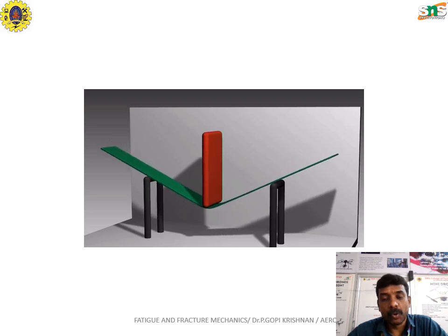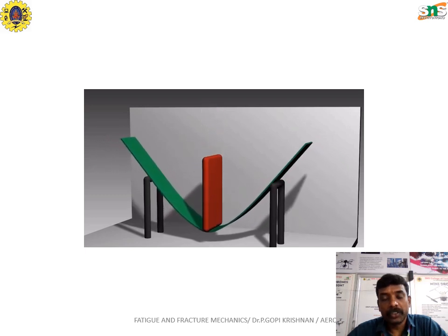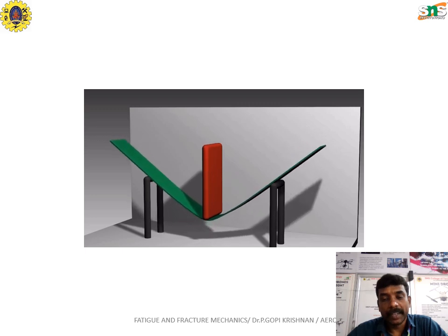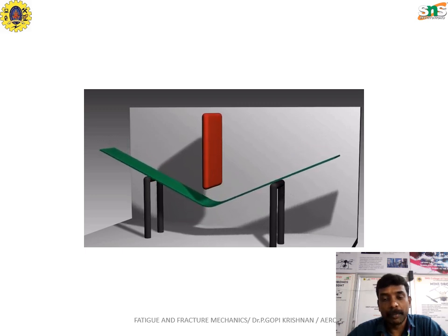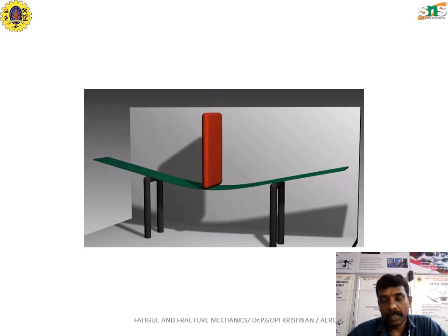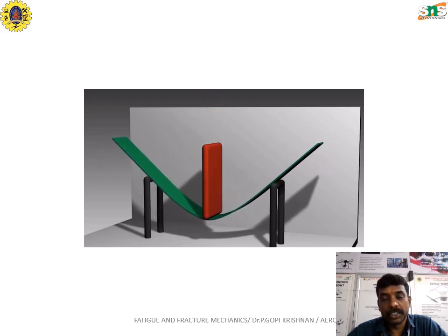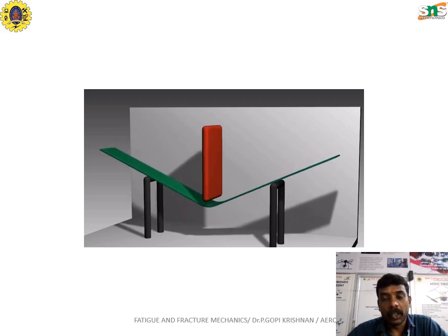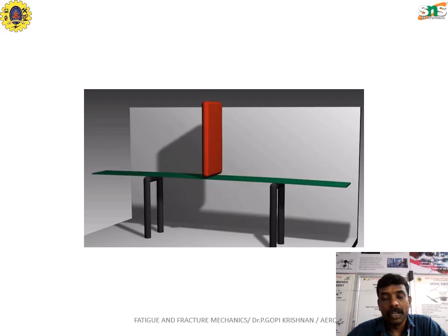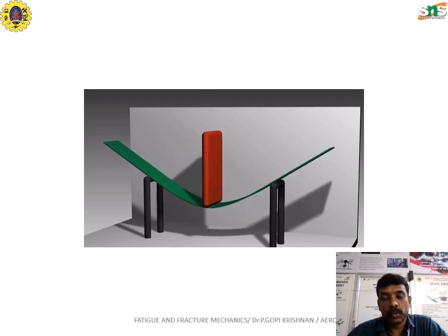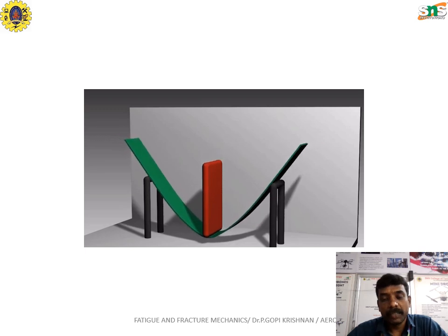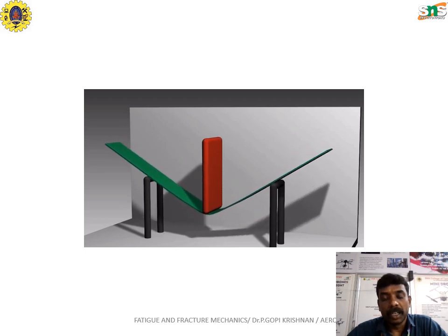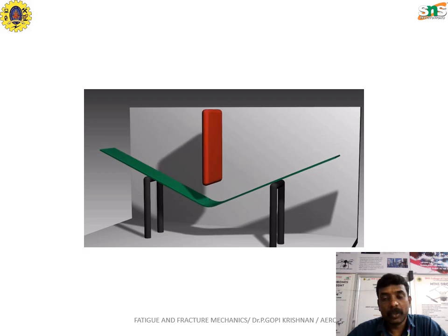In the picture given, if the same kind of force is applied over the sheet metal, in the top surface the force acting over the system can be called the compressive force, whereas the opposite side, that is the bottom side of the sheet metal, experiences some kind of elongated stress, which is called a tensile force. So this is the combination of the previous two diagrams, in which both the tensile force and the compressive force are acting together in the bending test, and this kind of test can be called the bending test.